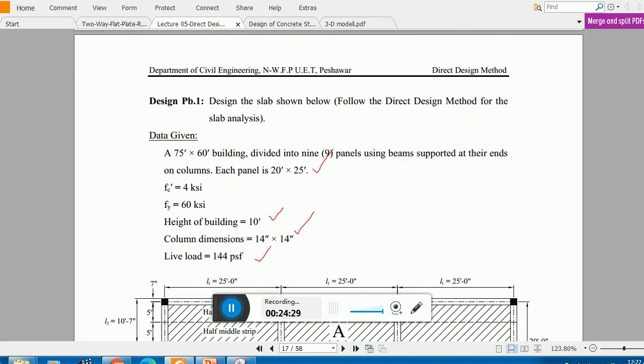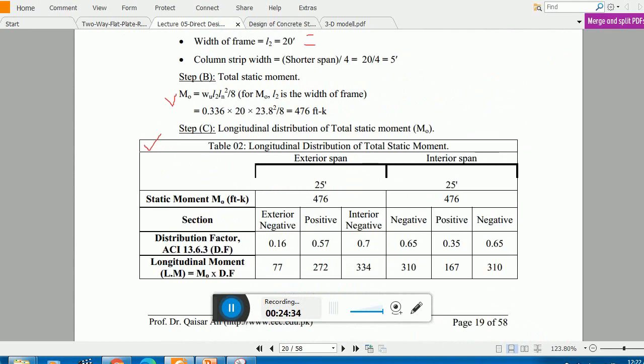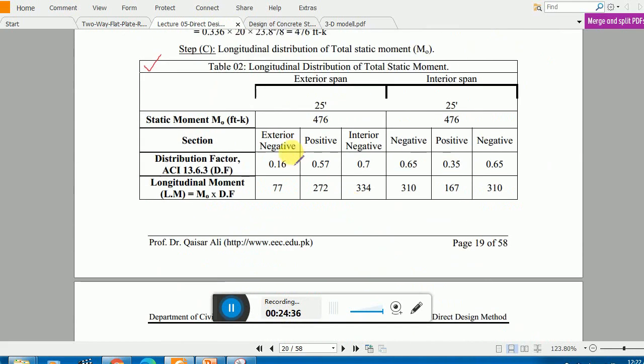Although in case of a flat slab system these are different. This is the only difference between that example number 1 and this example. So you see the coefficients, these are the longitudinal coefficients. I just picked those coefficients, and this is my end panel, and this is my interior span. Remember, you see exterior span and interior span. The M0 moment you see here, similarly the M0 moment you see here. Now you have to multiply 0.76 with this one, and you get this one.